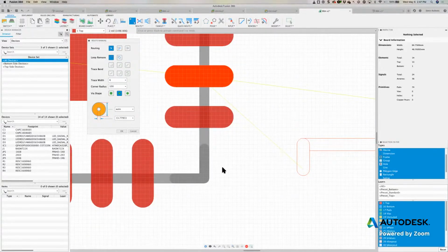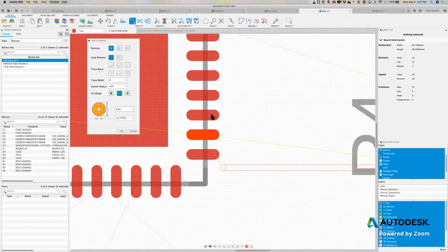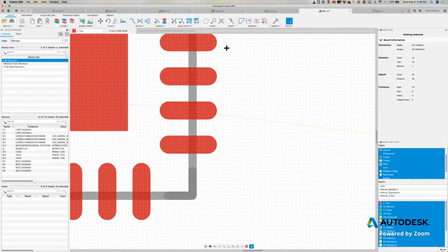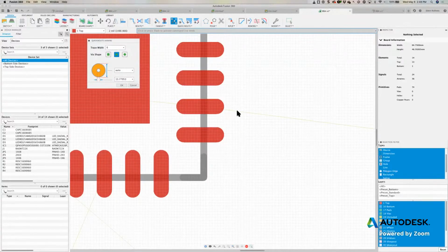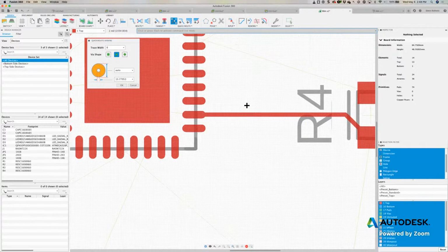So you really got to be careful that you're looking at your hatch lines. That way it lets you know if you have any type of DRC, because DRC is live, okay, as well. Now we do have a nice lineup of manual routing tools. So you could do multiple lines with differential pairs, meandering, quick route. I'll show you how to use quick route really easy. So I could just click here where it says quick route airwire, and I'll select a line and it will try its best to route that line, as you could see there. And I could do it line by line.